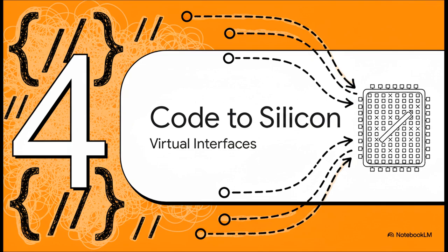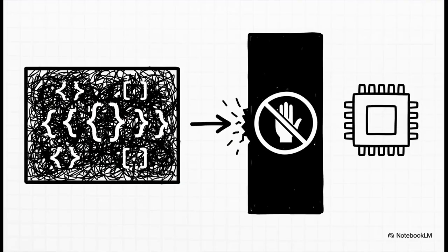How does our software actually connect to or touch the silicon of the chip? And it turns out there's a pretty big roadblock. You see, to make it reusable, test code is usually kept in this self-contained thing called a package. And there's a strict rule in SystemVerilog that says code inside a package cannot directly reference the hardware design. It's kind of like being locked in a sealed room and told you're not allowed to touch anything outside.